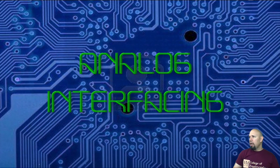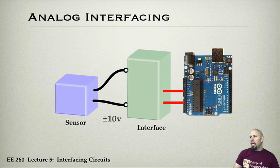Okay, now we're going to move on to talk about analog interfacing. Again, the concept of interfacing is that we may have some device like a sensor which runs on maybe plus or minus 10 volts. The Arduino runs on 5 volts. So we need some kind of circuit that will connect this kind of voltage up to our Arduino. Here's, for example, an analog signal that goes into analog channel 1 and ground.